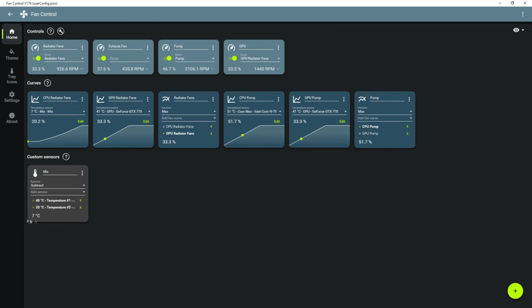I mean, 7C delta T is pretty good. Obviously, that's not actually a real reading there. But yeah, if you were setting this up, you probably want your fans close to maxing out at, well, definitely not maxing out at like 15. You want to try and target around 10. 5 to 10 is optimal, just if you want some recommendations there.